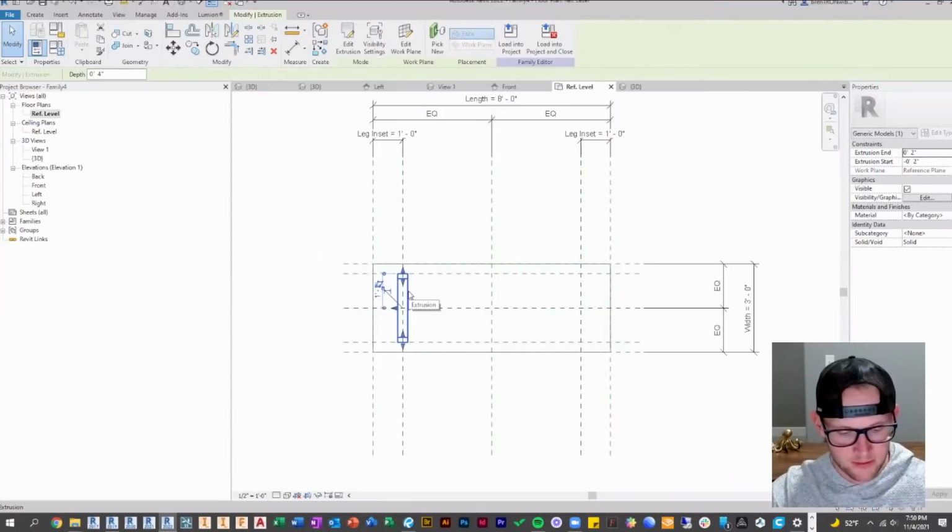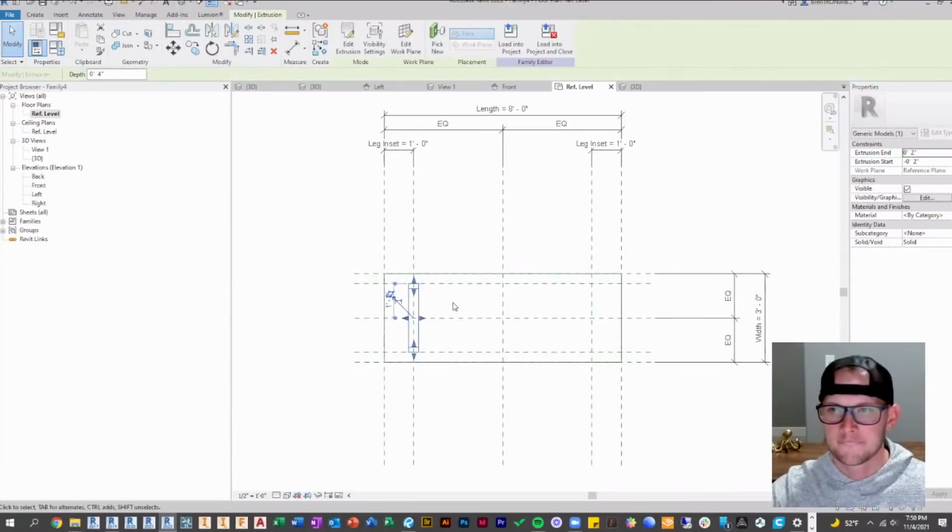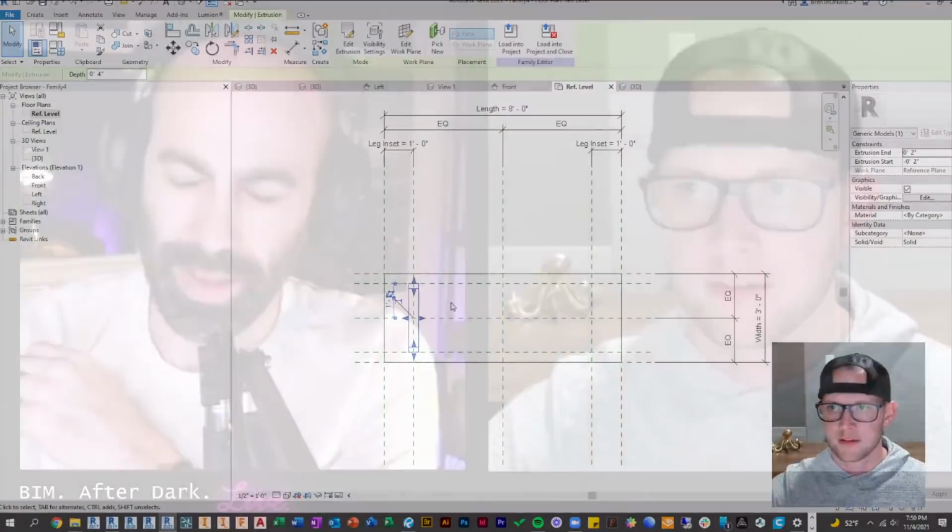That's actually pretty neat. Usually the initial instinct, and I'll do it too, is you just pull, you're going to push it away, right? And it will work, right? If you push it away, you lock the geometry. But to your point, even though it's working, the work plane of that object is still that middle plane, right? Even though you've pulled it and pushed it and you're using all the reference planes to keep it in place.